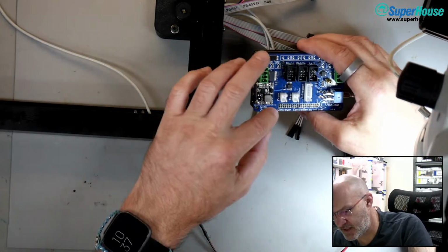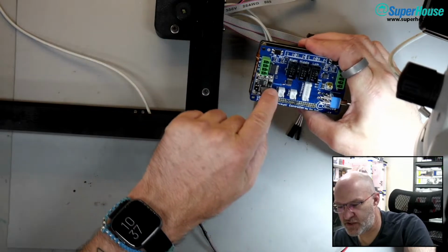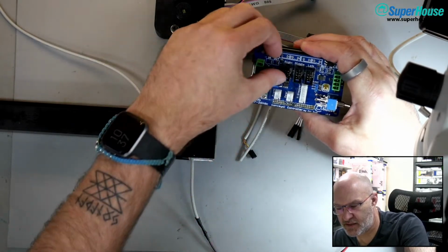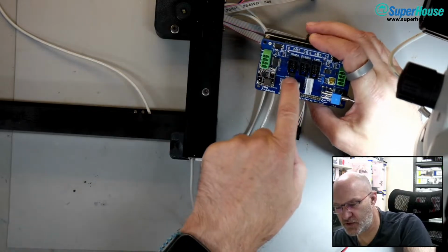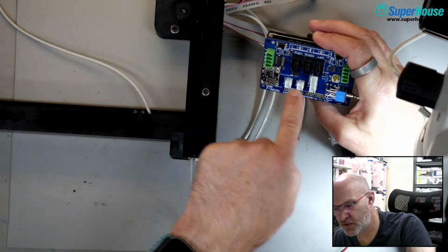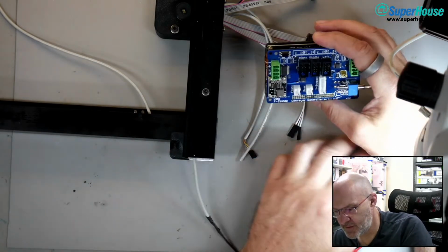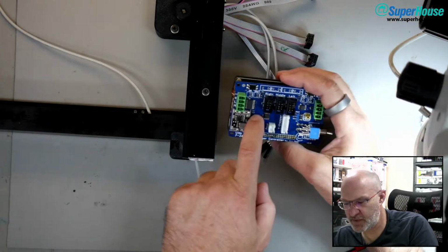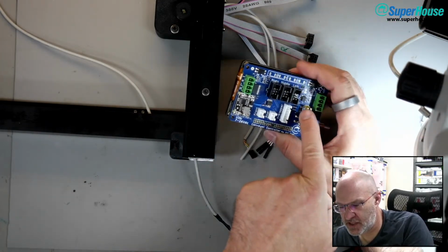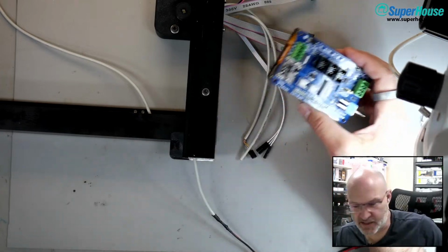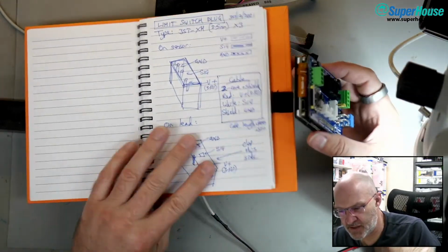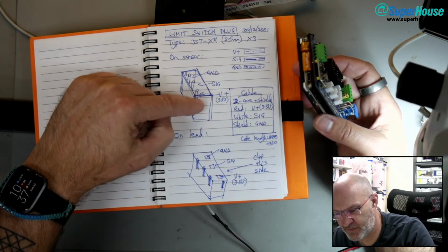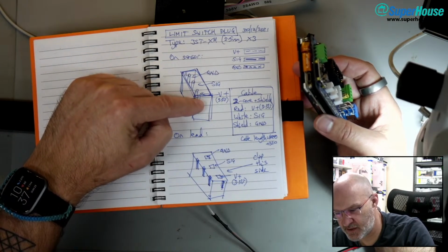So by connecting it, I cut the track to the 5 volt rail, and I put a little bodge wire on there that goes from the 12 volts in going to the H bridge. All right, so I need to revise the PCB for that. I also need to revise the PCB for the Y limit sensor because the pin ordering...